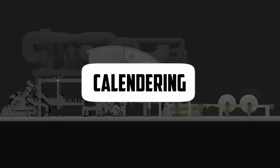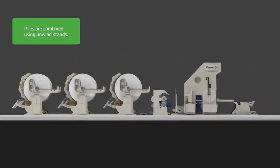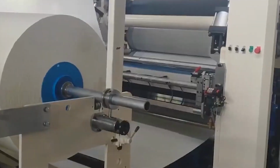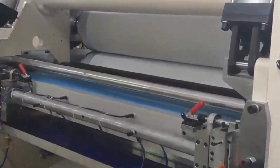Calendering. Calendering is a significant step in tissue paper production that refines the paper's surface finish, enhancing its smoothness and overall quality. After the tissue paper has been dried, it can undergo the calendering process. In this phase, the dried paper sheet is passed through a series of heavy rollers under controlled pressure and temperature.